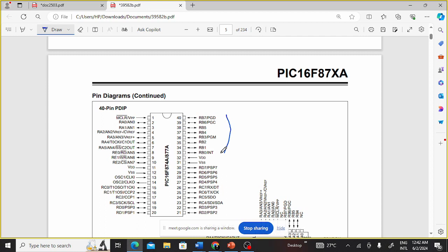Maybe this pin just sees a high. Let's say you create an emergency button, and that emergency button is connected to VCC. Once you press it, that's the rising edge. It will just trigger an interrupt. Maybe an emergency stop, something that just happened. And I did this in my inverter code. Maybe later in the day I will explain that.